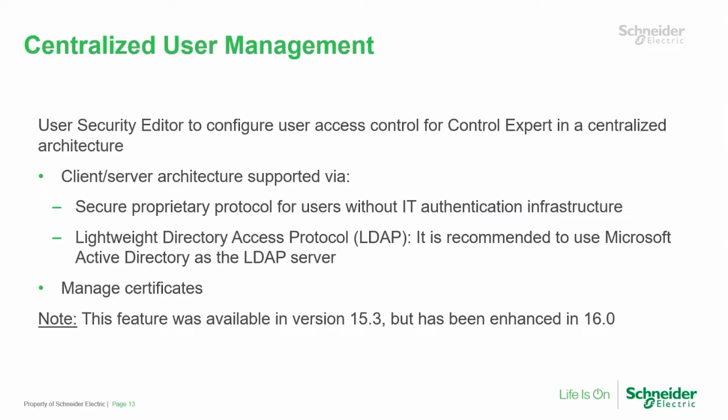So you might have a group of users that are engineers and you want them to have full access to make any program change they want to a PLC. But you might also have a maintenance group where you only want them to have read-only access so that they can troubleshoot but not make program changes. So the role-based control helps with a little bit more than just cybersecurity.